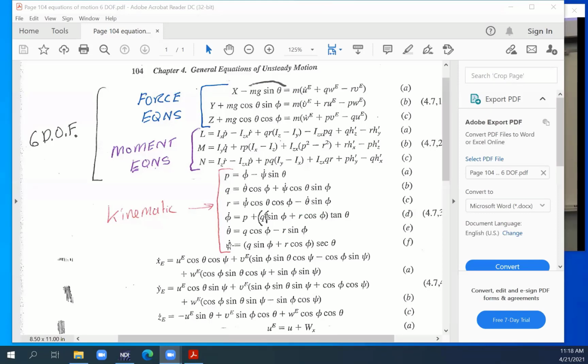Now, if that sounds like there's a lot of error that could build up in this, it can, because if you fly for an hour and a half, there's little tiny errors that build up as you do this, and that's just numerical integration error. And so what he does is a fourth order Runge-Kutta method for two reasons. One, it's fourth order, so it's actually a lot faster than our first order method that we did. It predicts with an aircraft design, they'll develop the equations of motion, they'll do wind tunnel tests to get the forces and moments right.